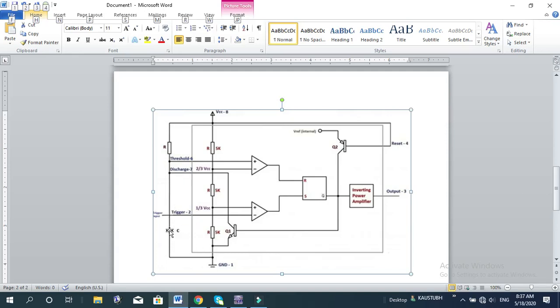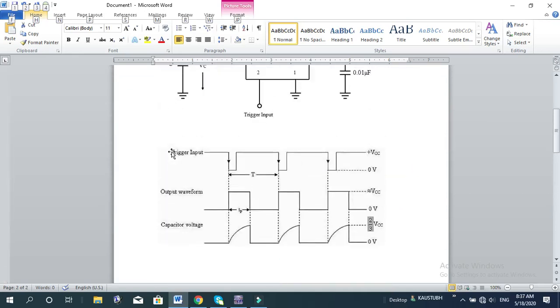So how will it start charging? Through this resistor R, because this R is connected with the VCC. So it starts charging, and as you know, the capacitor always charges up to 2/3 of the VCC. So the capacitor now starts charging towards the VCC, through the resistor R. This R here, I had given it as RA probably.